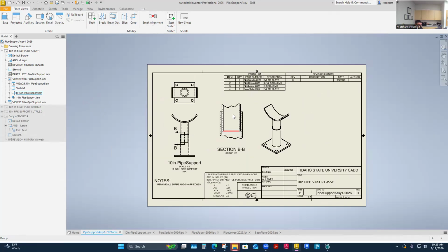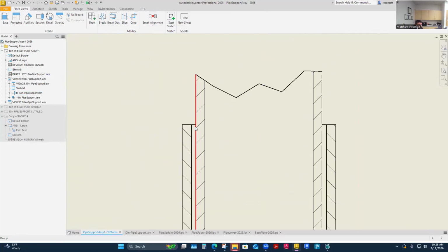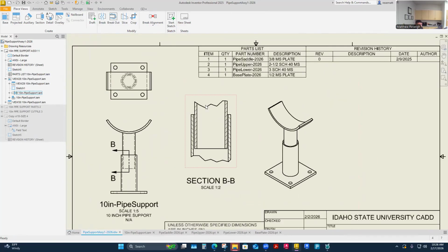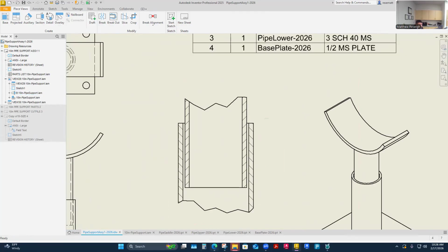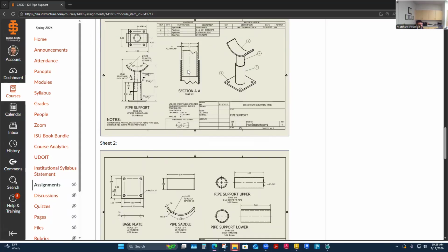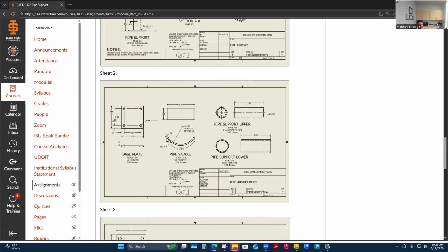Yeah. And the biggest thing is I just need to tell people what that clearance is. But if I check my own, I did add a center line. Good. Add center lines. These things need center lines, center marks, pull them together. A few dimensions with descriptions. I need to build this though. This is just individual parts. So I'm showing them in their kind of finished form, right? So like this one, I'm showing it when it's formed up.